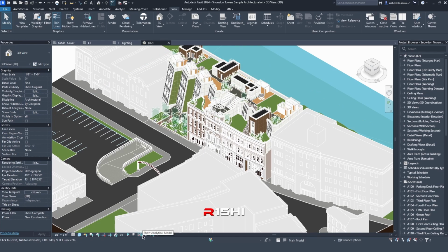Sometimes you have many views which carry similar settings, so it is very difficult to go to each and every view and assign the same settings. In such cases we use a concept called view templates. Those are there in Revit over here, and you can use them. In future we might see a detailed lecture on this part too.